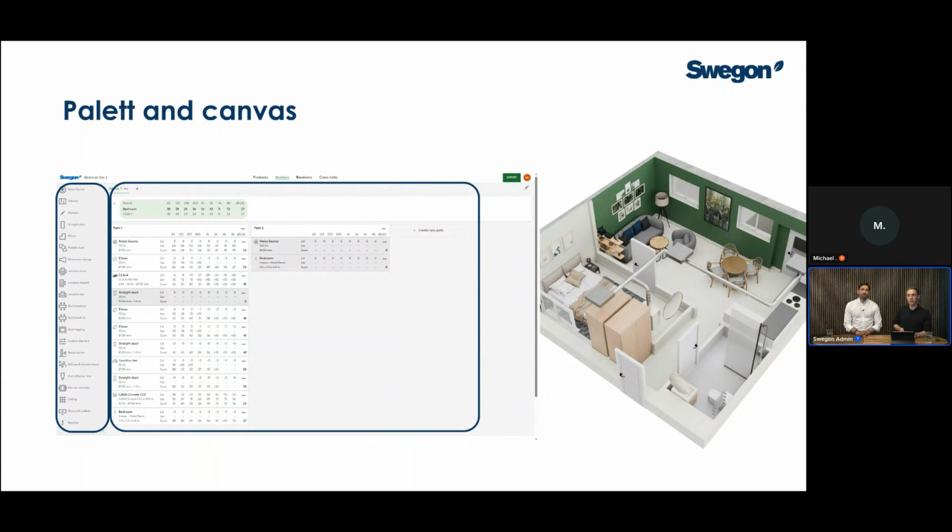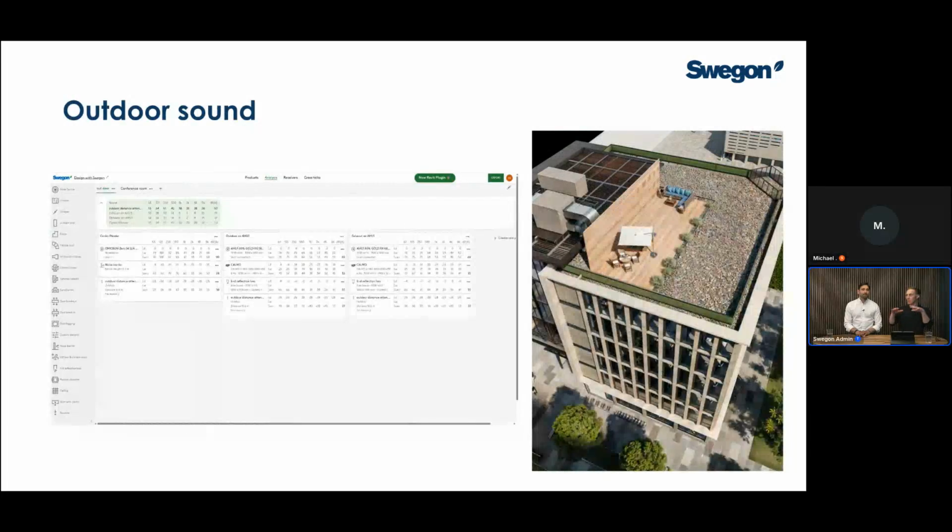That's an indoor calculation. We could move up to a rooftop and consider that we need to calculate the air handling unit, and maybe especially a chiller, which can have quite high sound levels at its worst day per year. And imagine if you have a relaxing area, a patio, where you have a demand of 50 decibels. Could that be achieved with a 10-meter distance? In this case, I did the calculation. No, it didn't. I had to put in a noise barrier, which is also a function, to see how much it would attenuate the sound coming from these sound sources.